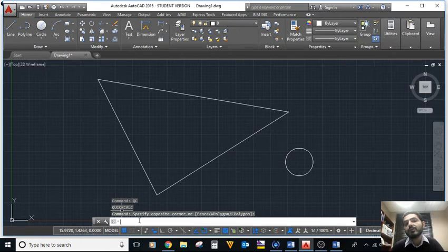So what you need to do is to create a block. That block is a predefined drawing that you can define, or you can get something from AutoCAD that's already drawn for you. It's pretty much like a library. You are creating your own library of different cross sections or drawings that you can pull out at any time and insert where you need in that drawing. So every time you come up with a new drawing, you can spend more time on the unique and new elements of that drawing. But once you see a kitchen or a bathroom or a balcony design, you can pull it out from that block.